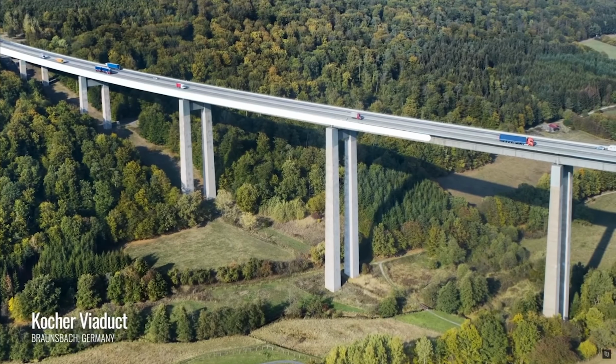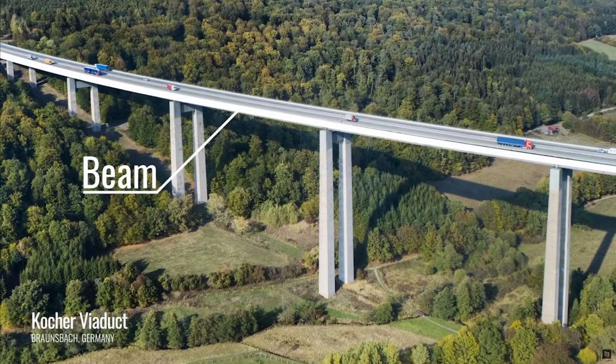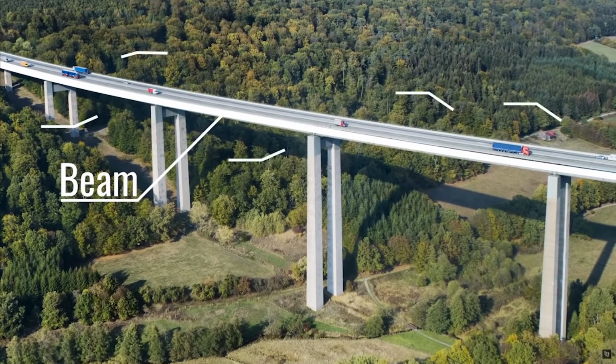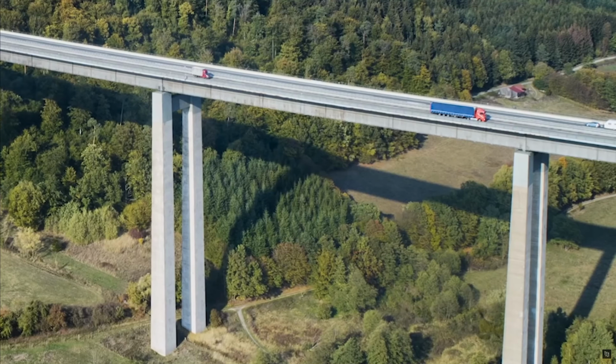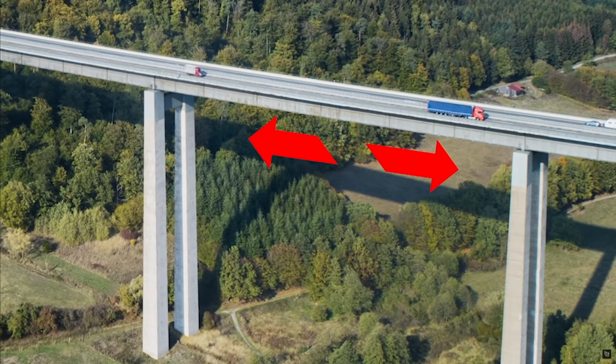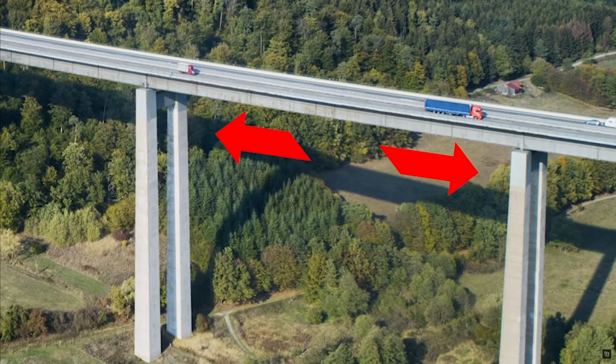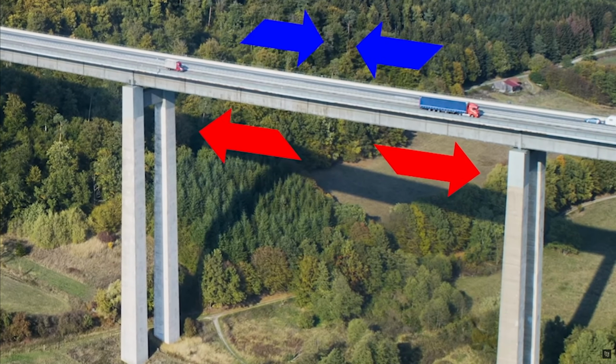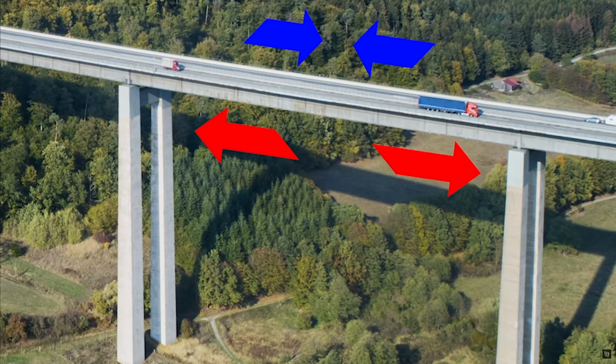For instance, if you have a beam, now a beam is a long member that is meant to span from one support to the other support. In many typical cases, the beams are supporting the loads transferred from the deck. Well, in the middle of the span, these beams are often bending or experiencing stresses or a force that causes a bend. Well, in this case, you're going to have the bottom of the beam that's going to be tempted to be stretched. That is a tension force. However, the top of the beam, as it bends, is going to be experiencing a compression force because at the top, it's going to be shrinking.